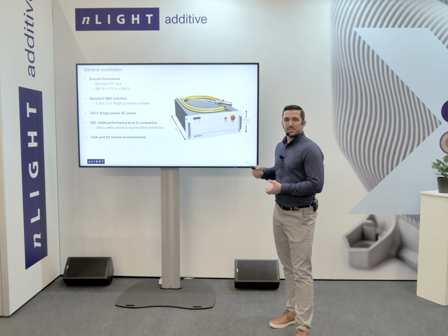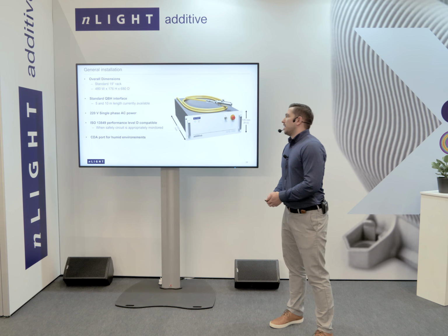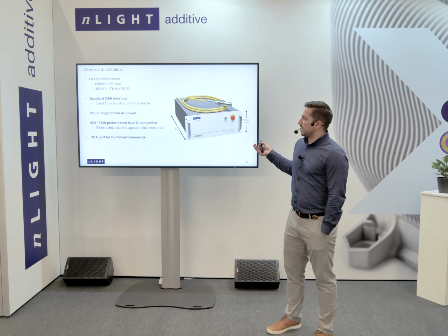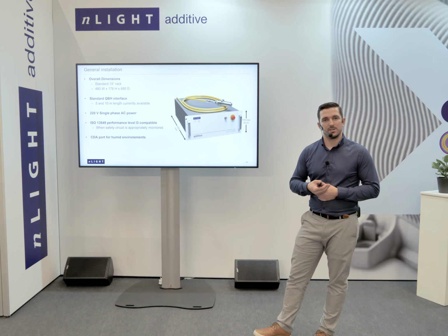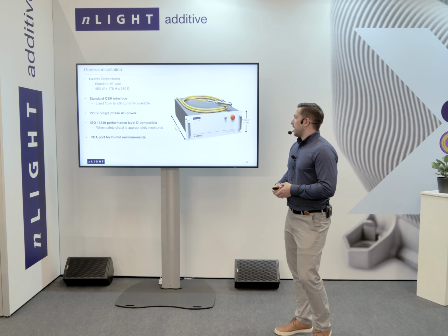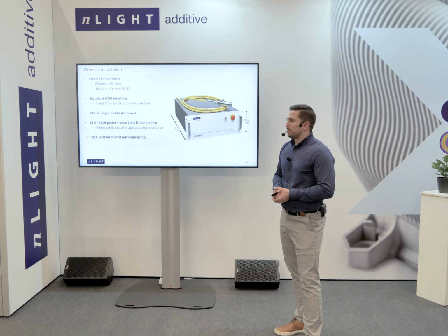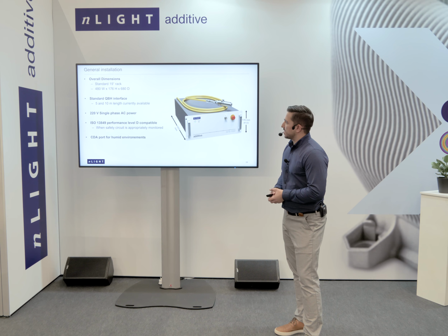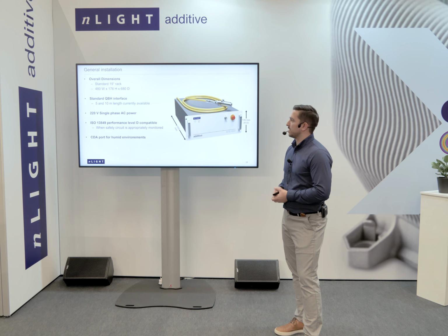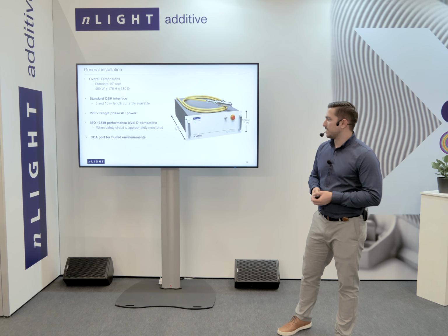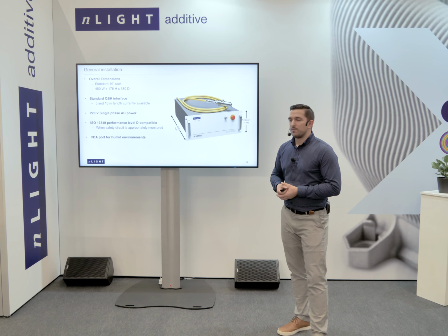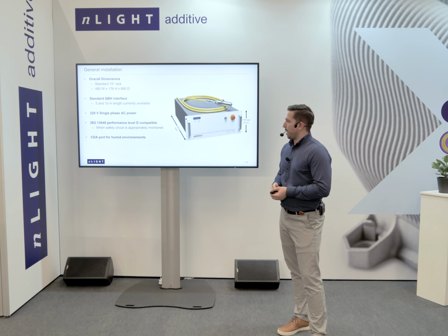Back to the Afx specifically and integrating it into your tools. We've leveraged our existing design extensively, so it's basically a drop-in replacement for any of our standard CFL lasers today. It's a 19-inch rack mount box and is 4U high. It comes with a standard QBH interface. 5 and 10 meter lengths are standard, and it's powered with a single-phase 220 AC input.